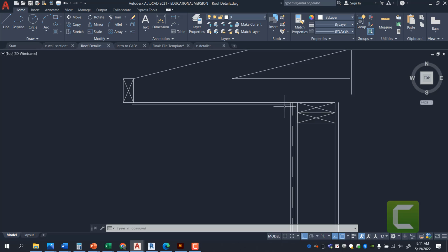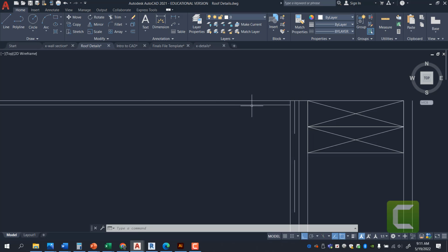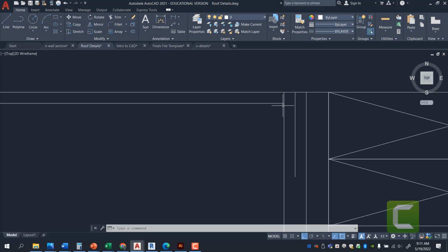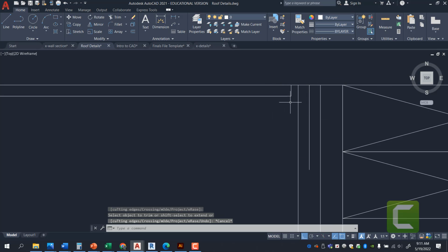Now, just to cover up this joint, because you need room for your soffit board to expand, so in reality you might cut your soffit board just slightly shorter. There's no need for any type of caulking or anything here required.